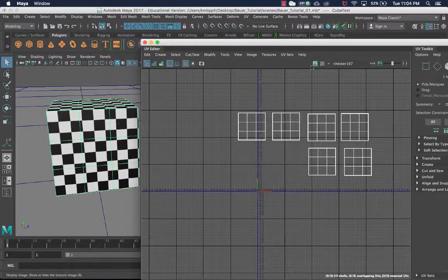So in order to do that, I want to organize them in a correct manner. I want my 4 faces that are kind of the middle of my cube. So if I were to take out my top and my bottom, those 4 other sides, I want to be able to lay out flat. So like we talked about with a Coke bottle, and if you were to roll that label out, I want that same general idea for those 4 sides of my cube. Right now, if you look in my UV editor, you can see that all 4 of them are disconnected. None of them are working hand in hand or side by side.